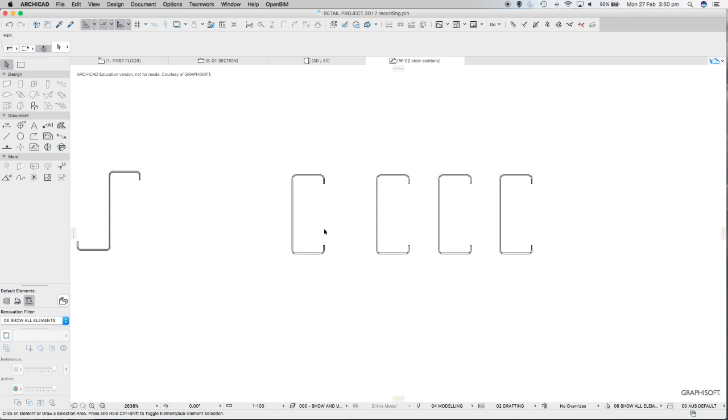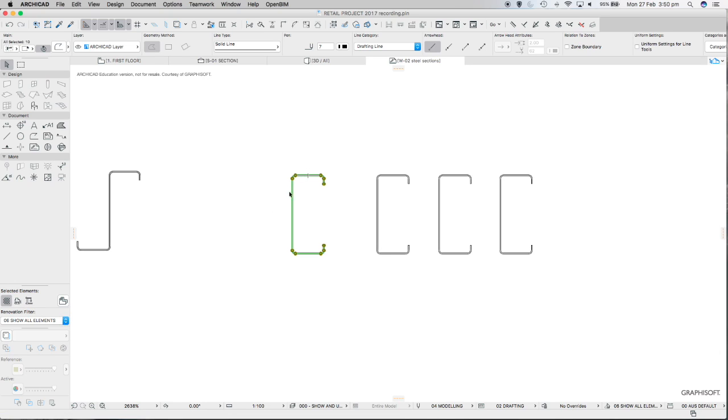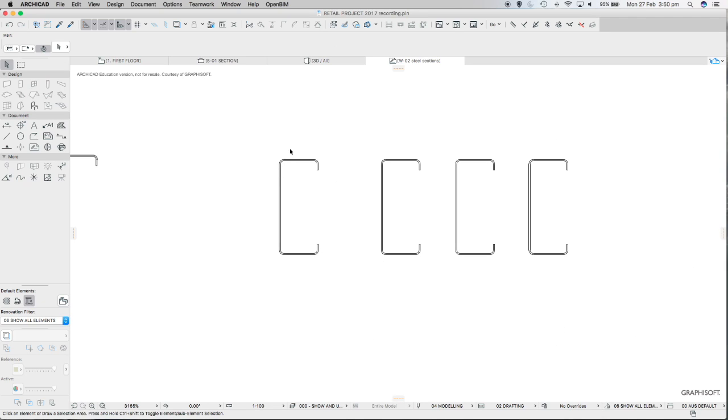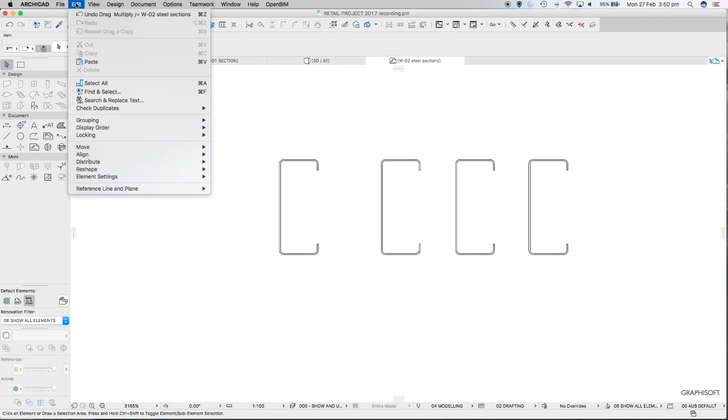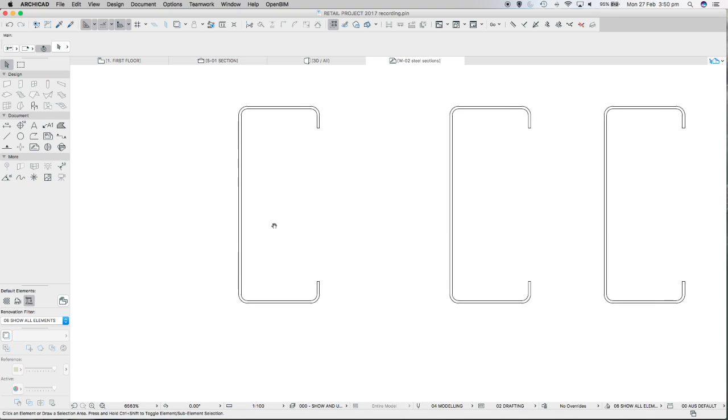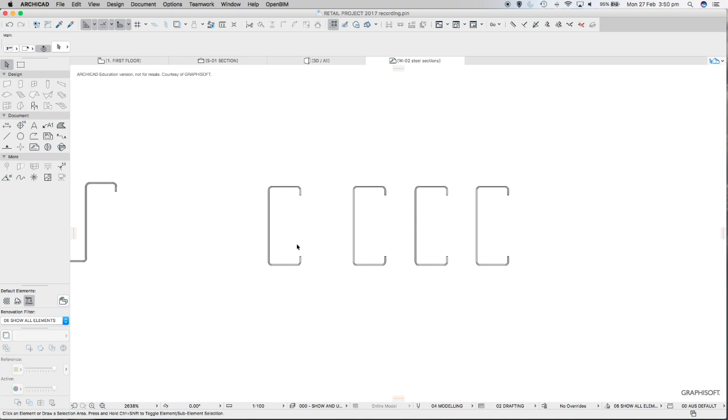So probably the first thing that we'll do is we need to be able to change these shapes. It's one entity at the moment. It's probably combined as a single polyline. Now we can work on individual bits of that polyline. If we go up to, I think it's under Edit, Grouping, and we suspend groups. So if you click Suspend Groups, that'll allow you to put the different parts of that polyline aside to be worked on individually.